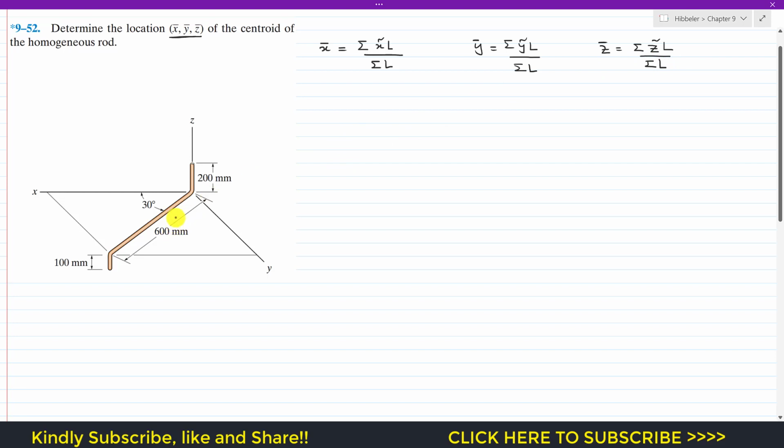So to find the centroid of this composite shape or body, we have to divide this into different segments. So let's say this is our segment 1. Let me write that this is segment 1, this vertical portion. Then this horizontal portion is segment 2, let's say. And this third vertical portion is, let's say, segment 3.